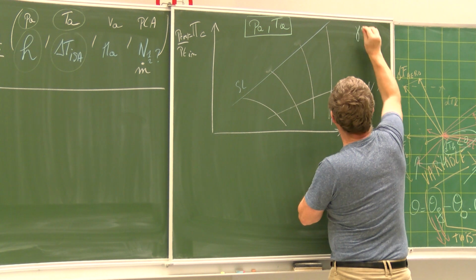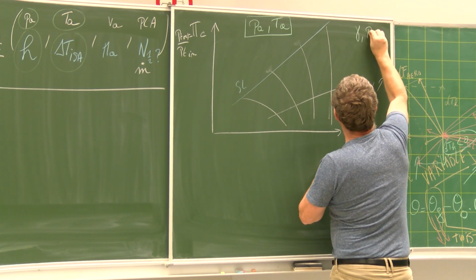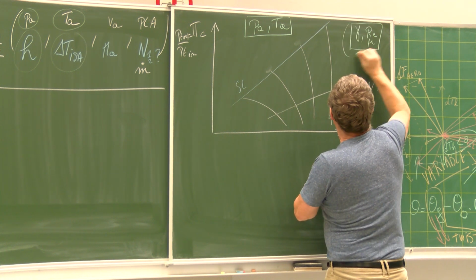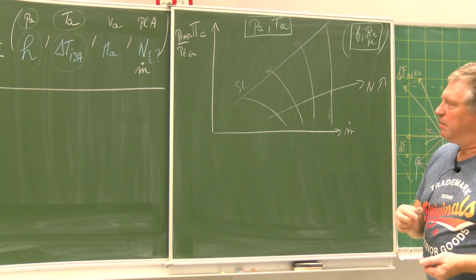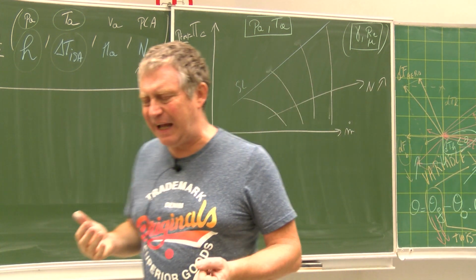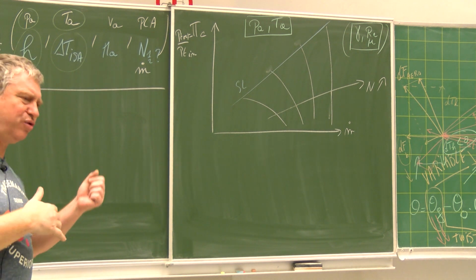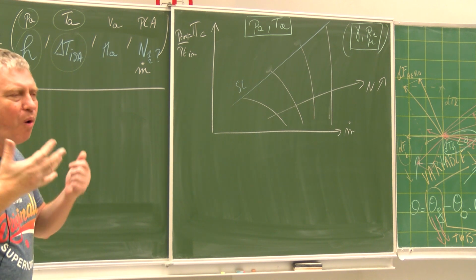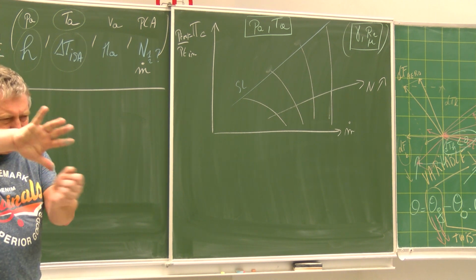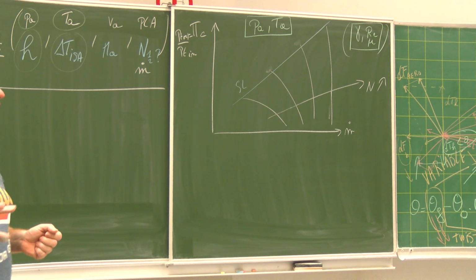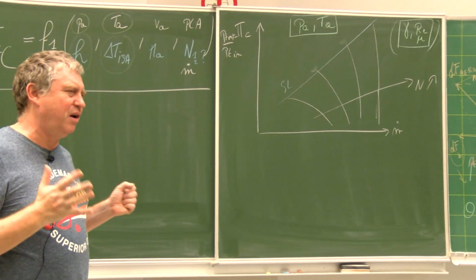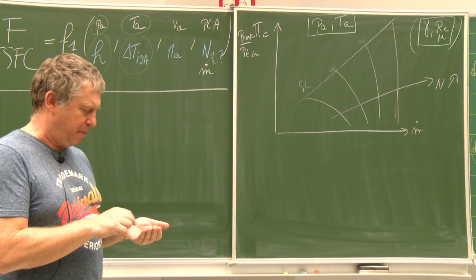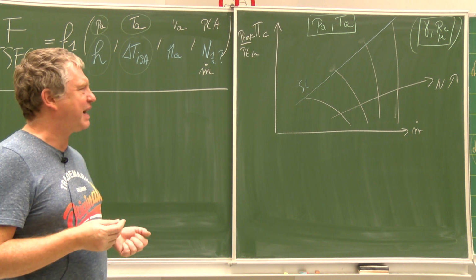Also, for every gamma and every Reynolds number or viscosity, this is also to be considered, but normally we work with air, normally we are at high altitude, so the Reynolds number is high enough and not too small, and very often these 2 parameters are considered but put a bit on the side. Of course, there are exceptional cases or special cases where you will need to consider gamma and the Reynolds number, but very often in the compressor it's not the case.